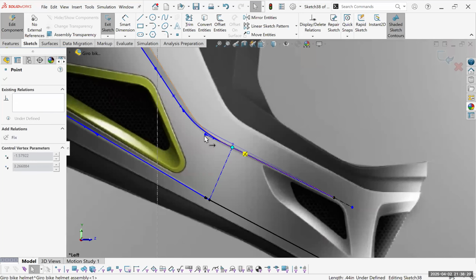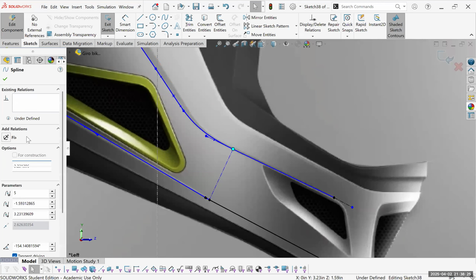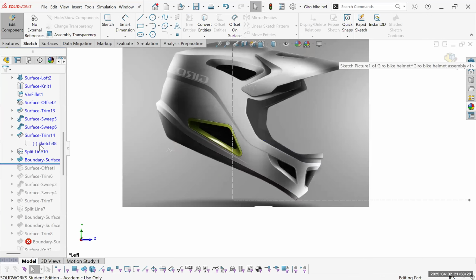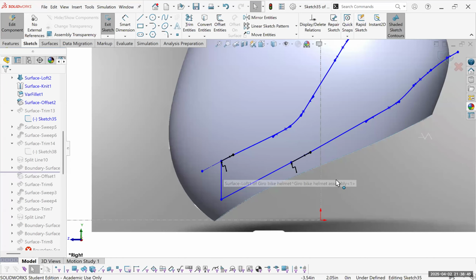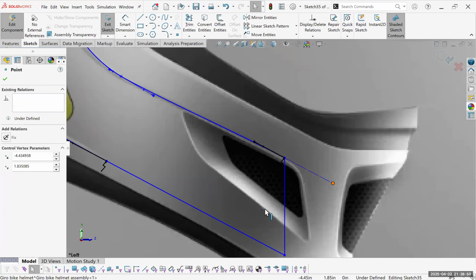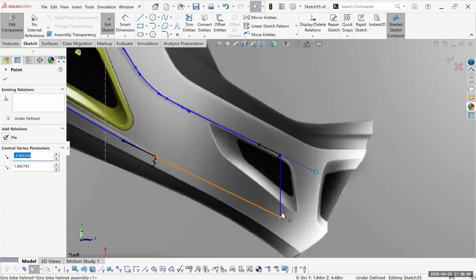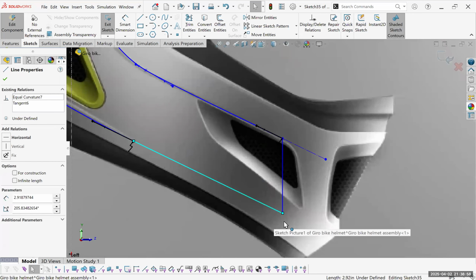We just need to have a slight cut over here on our chamfer. Then I go back to my original cut. This is my trim. Here's another trim. Okay, let's look at this one. Okay, this is where the issue is coming from. So this one was pretty open. Oh, I think I set these two to be parallel. Maybe that's where the issue is coming from. Just gonna open up. Not gonna have them be parallel.